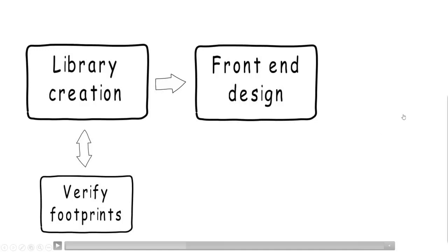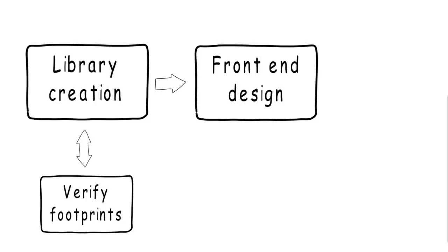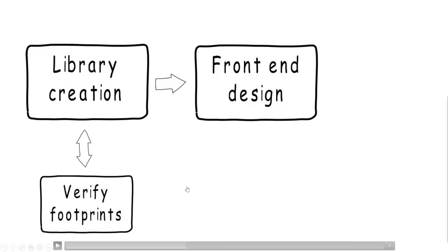So when we get to the point of placement and assembly review with the contractor, you're never going to run into issues because you've already validated that footprint against your or your contract manufacturer's DFA rules, so that you don't have to go back and fix footprint related items later on. And we'll talk about some of that here in a minute.